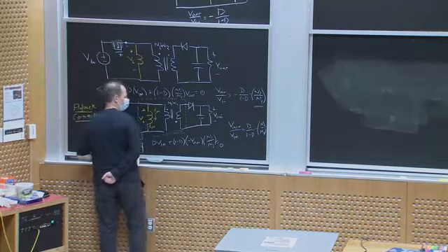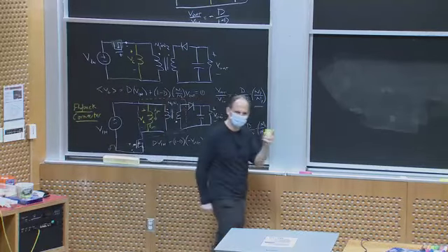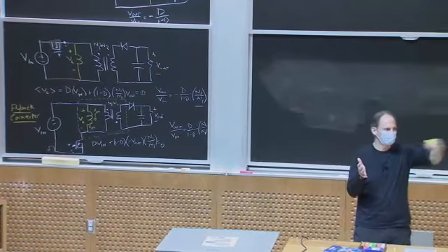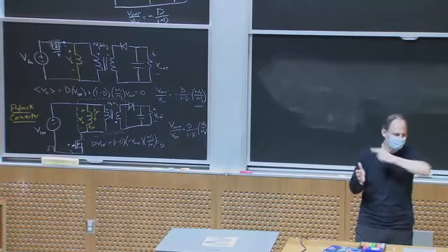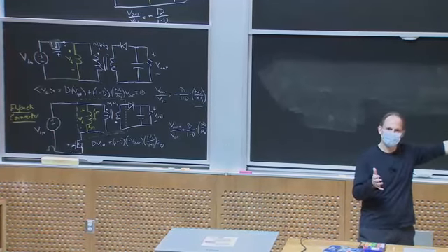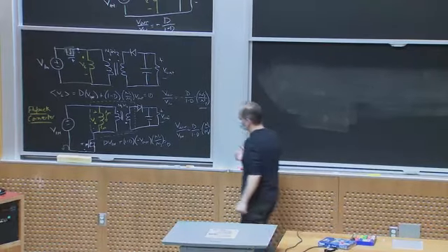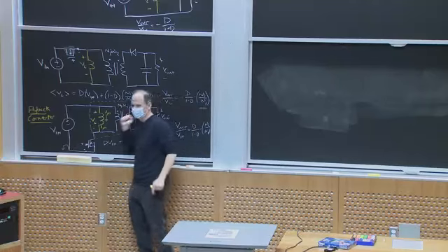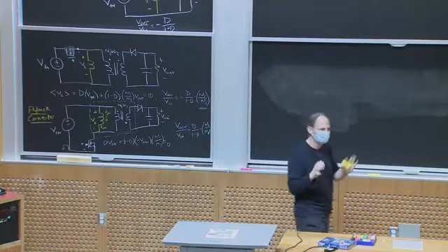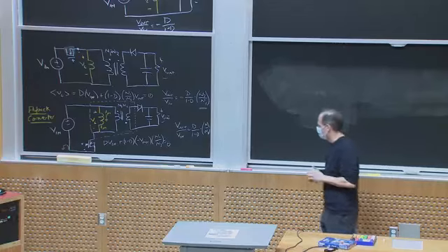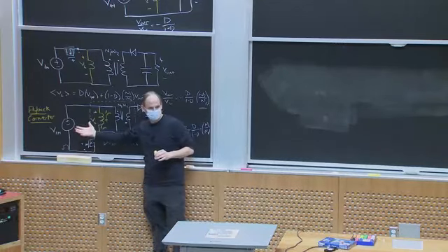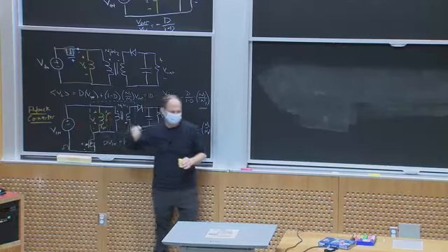I believe that where the term comes from is back in ye olden days when you used to have a cathode ray tube and you'd have some really high voltage causing the cursor to kind of swing or fly. This was the kind of converter that was often in that because it got used to generate the high voltages. So it ended up being called a flyback converter as far as I understand it. But a flyback converter is essentially just an isolated buck-boost converter. Okay?